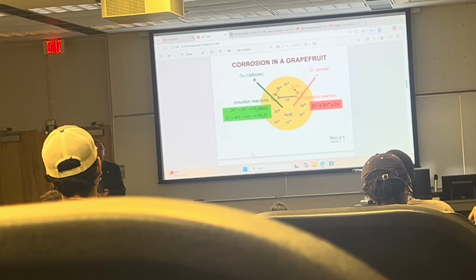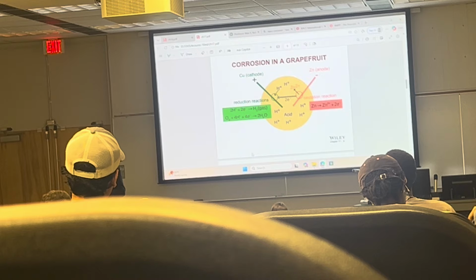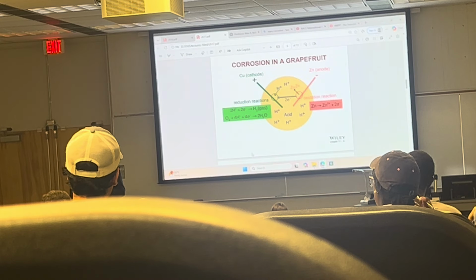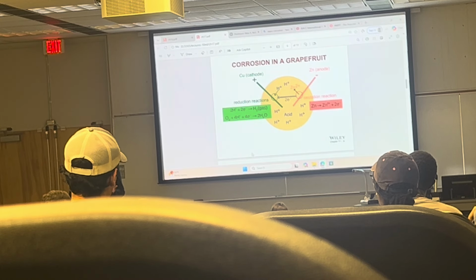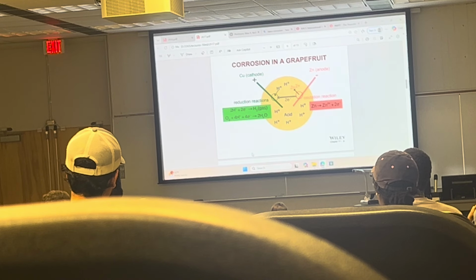Which way would it bend? Which way would it bend, downwards, right? Yeah. So you would put it on the top part. For the floor. So here's my floor. It's supported like this. I'm walking on it. Where's tension? No, on the bottom. The bottom.